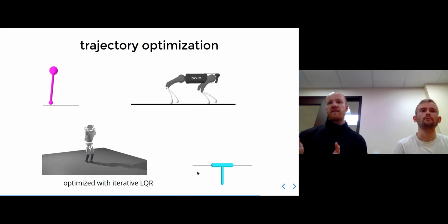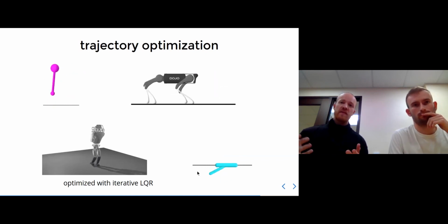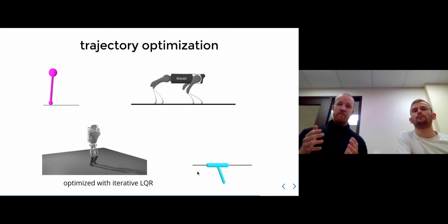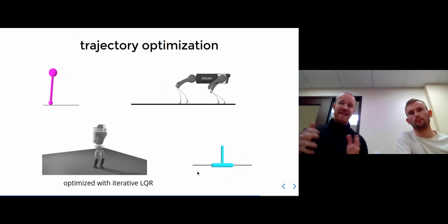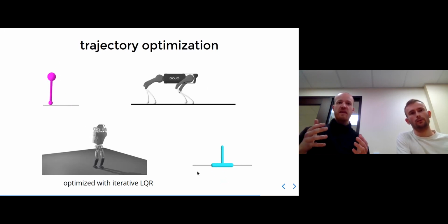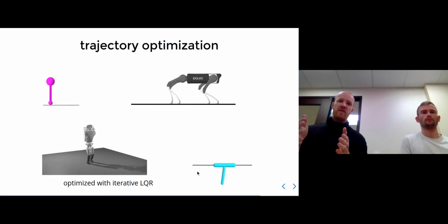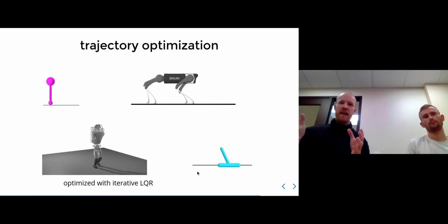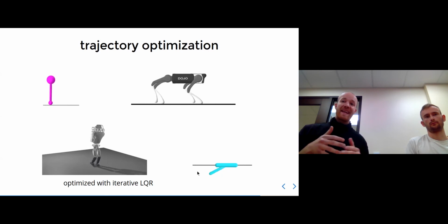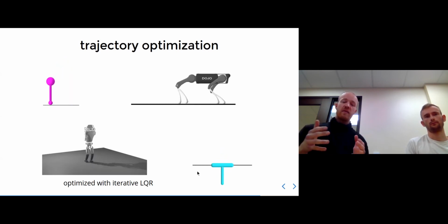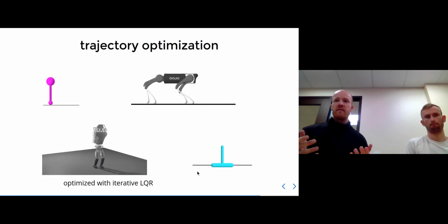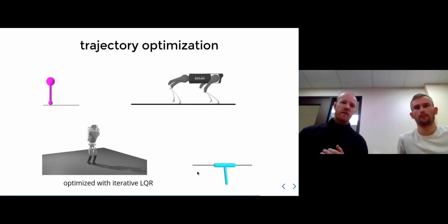On the right, this is the Unitree A1 robot. Here, we basically designed a nice kinematic trajectory that's dynamically infeasible. And then in the cost function, we basically regulate to this kinematic plan that we like, and LQR is able to find a dynamically feasible plan that looks really nice. And this is running in just a couple of minutes on a pretty standard workstation.